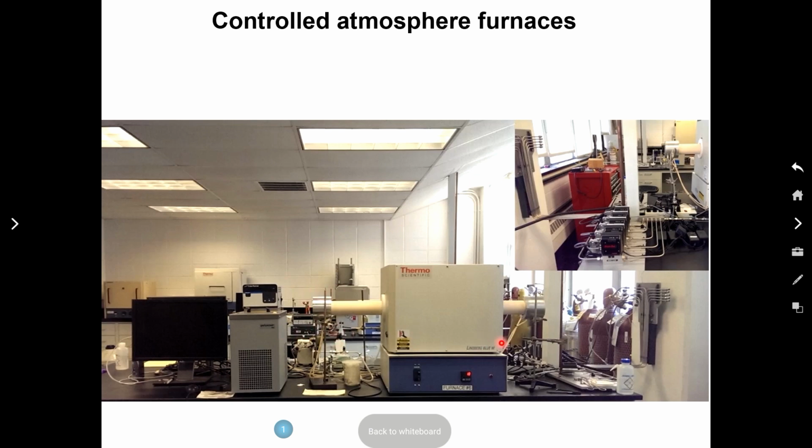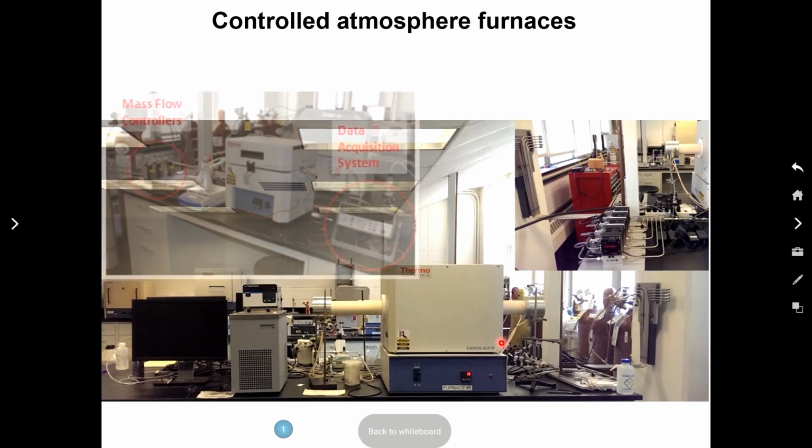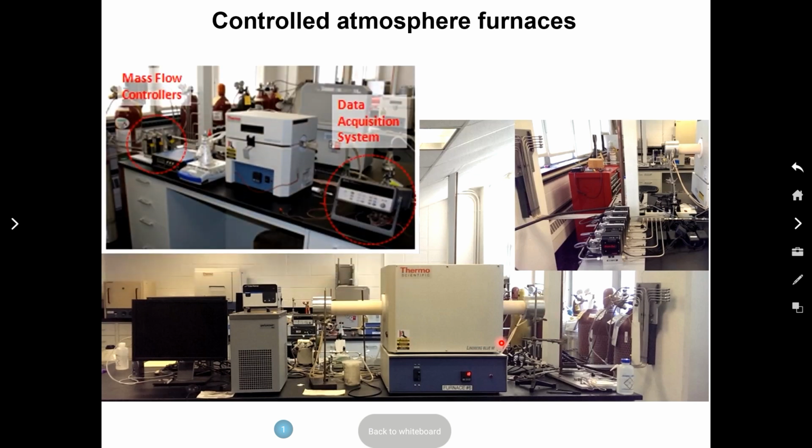The other option is a quartz tube, where you're not going very high. With a quartz tube, I think it's safe to go to 900, 950. You don't want to exceed that. Even for a short amount of time, 1000 degrees is probably okay. But if you want to go beyond 1000 degrees Celsius, you have to use ceramic.